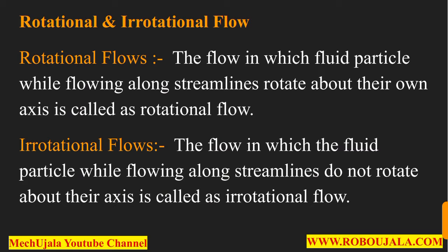Now let's see rotational or irrotational flow. Rotational flow is the flow in which fluid particles, while flowing along streamlines, rotate about their own axis. And in irrotational flow, the fluid particles, while flowing along streamlines, do not rotate about their axis. So that is rotational or irrotational flow.